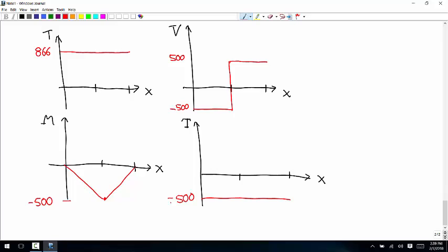And that says that as you approach x equals 1 from either side, the internal bending moment is getting bigger in absolute value. So what you would expect is that if this thing was going to break, the fracture would start somewhere close to this. You don't know which side. You can't pick the left versus the right, but you know that things are worse for this beam close to x equals 1 than they are far from x equals 1.